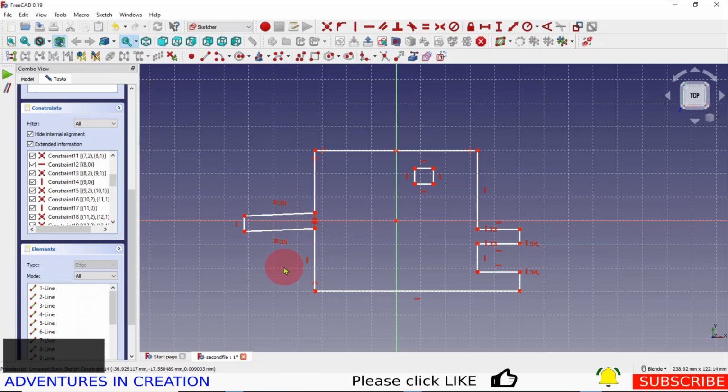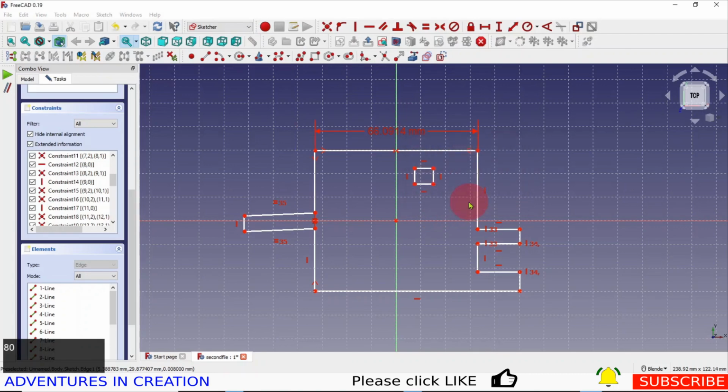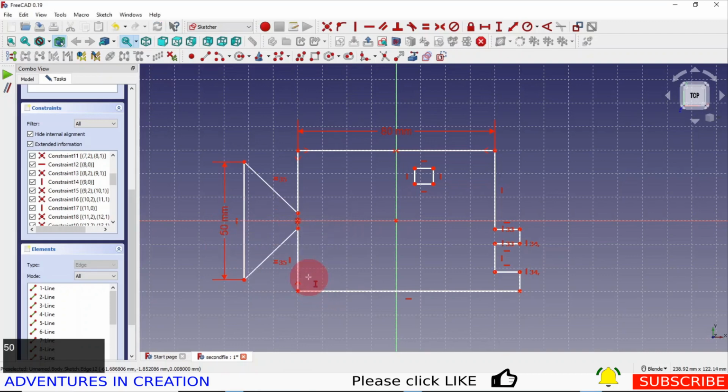So what we're going to do now is start adding some dimensions. So we're going to do a horizontal dimension. We're going to tell it this piece here, and we know that needs to be 80. So I'm going to make it 80. Now remember, I made this and this symmetrical to this line, so it opens up equally across that line. I also know that this should be 50, as that is what I had selected.